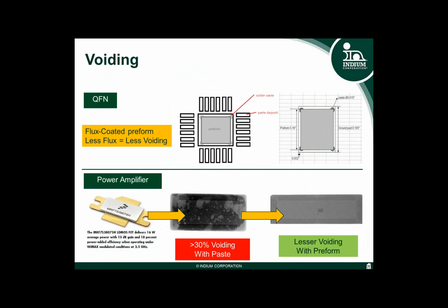In cases where the solder paste is not enough, or there is an entrapment of flux residue, or the design requires more solder volume because your component is possibly not even a flat terminating or bottom terminated device. It could be a J-lead package or a gull-wing package that now has an underbody that has been exposed for thermal transfer, but naturally is not interfacing directly with the PCBA.